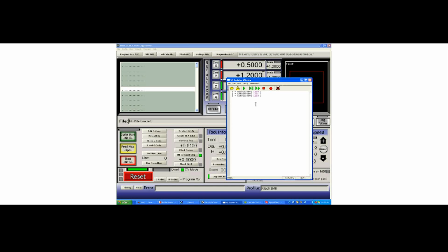Now there's another way that you can more tightly test that routine. If we push the single step button, and you can see a tooltip lights up when my mouse is over it saying step into program. If I hit it once, an arrow appears showing that I am on the first line and I'm about to run it. If I hit single step, we go to the next line. So we've just executed the X is equal to getUser DRO 1200 line.